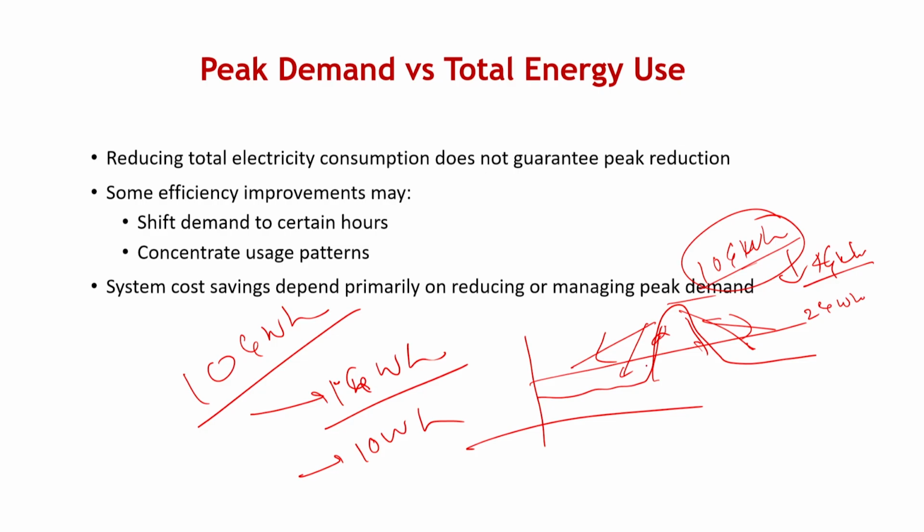And if this ramp up is not possible through the technology, then what I may end up doing is that, though my requirement is only 1 gigawatt hour for that period of the day, I may have to run that system at 4 or 5 gigawatt hour. One, because I don't want my generators to trip. Second, I may not be able to manage this fast ramp up. Since my ramp up can only be slow, I will have to work out the minimum generation at which I need to continue to run my system, so that I avoid tripping of the system.